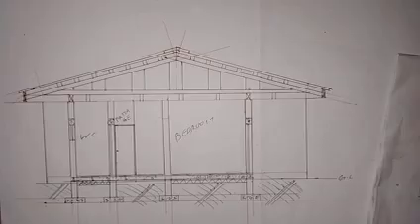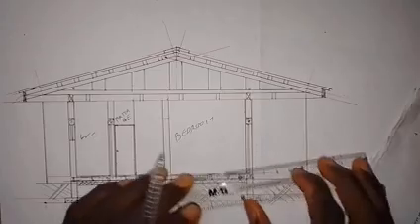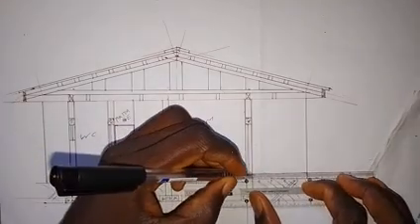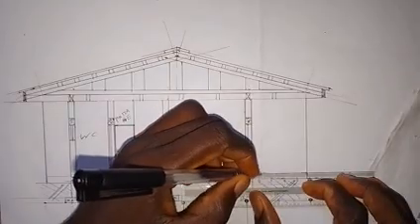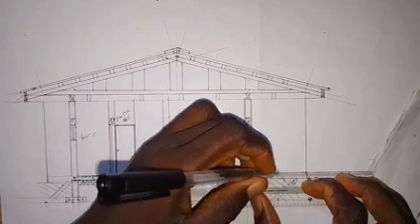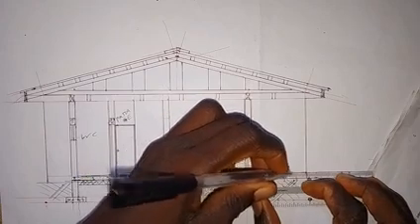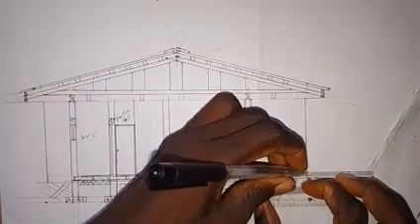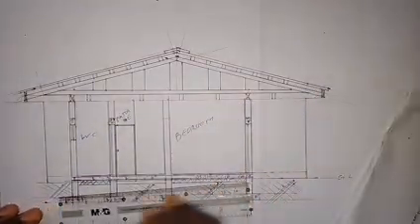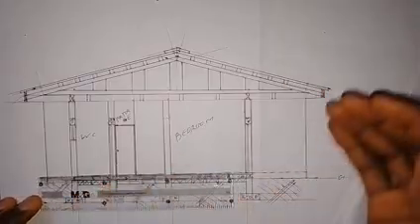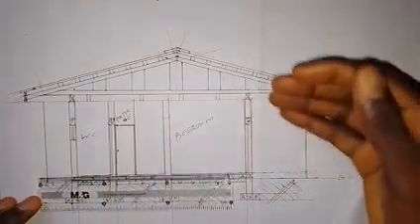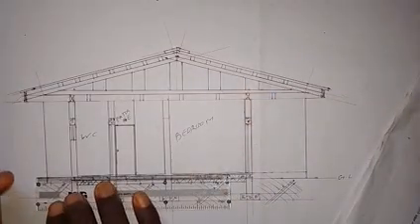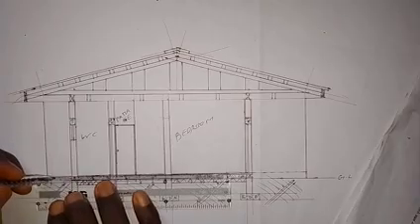And then I also need to, for this floor level here, we can't see it, so let's show it hidden with short dashes line for this floor level within this veranda. Though we can't see what is there, because there's a wall here that prevents us from seeing what is inside the veranda. Also, this is within a building, so we need to show this hidden.